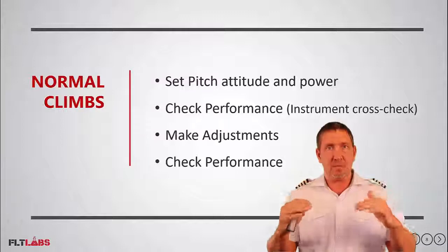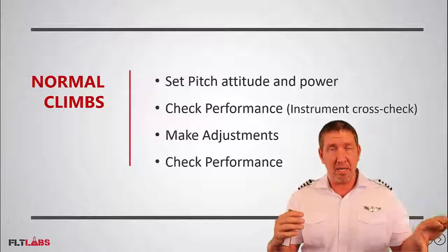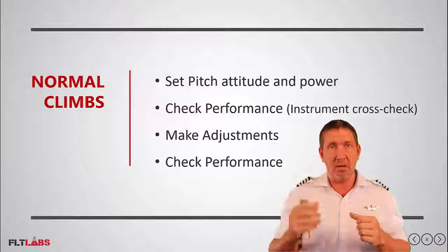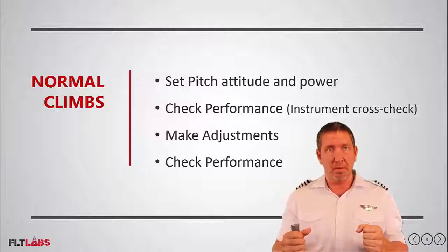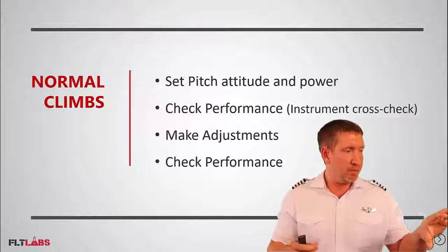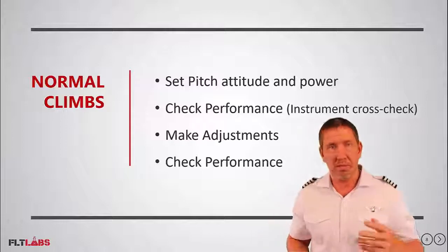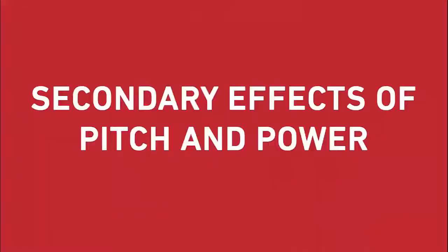Now I'm going to see while I'm climbing, I'm not climbing at 85, I'm actually at 95. So I'm going to need to look out, increase my pitch just a little bit more. I'm already at full power, adjust my trim, check my performance instruments, and that's the process that we go through when we're going to set a climb.